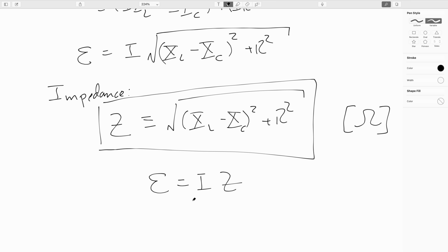So by billing them as if the phase angle was 0, that creates an economic incentive for factories to get their inductive and capacitive reactances equal. Now, why would they ever be unequal in the first place? Well, remember, a factory is basically just a bunch of motors. I know I'm greatly oversimplifying here, but there are an awful lot of motors in factories. And motors are just giant windings of wire.